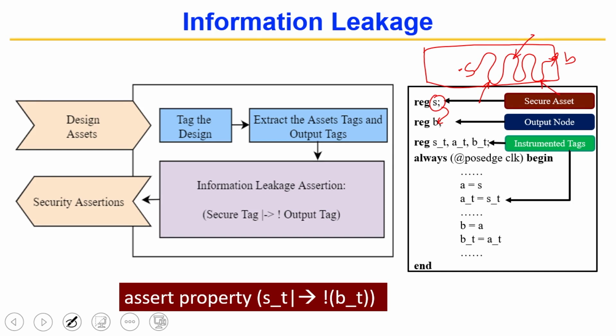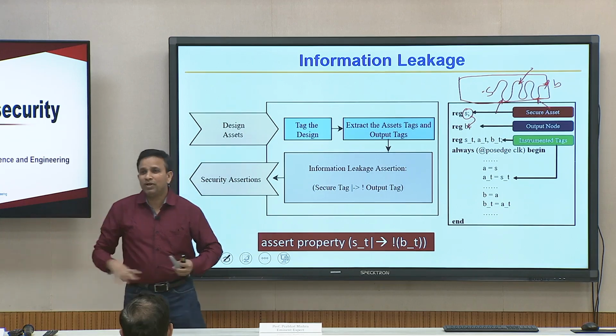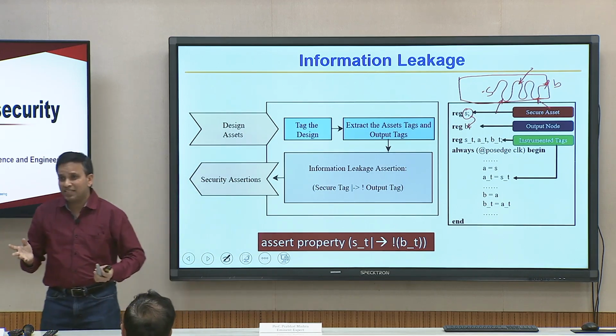The probability of each if could be very low, and if you multiply those probabilities, the probability of this path happening during simulation is extremely low. If you did not run enough test cases, in reality there is a leaky path, but it did not fail, and you will falsely assume that this design does not have any leakage problem.